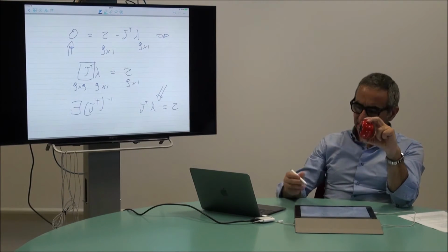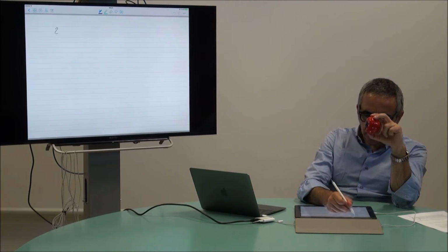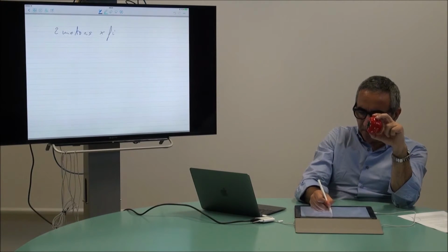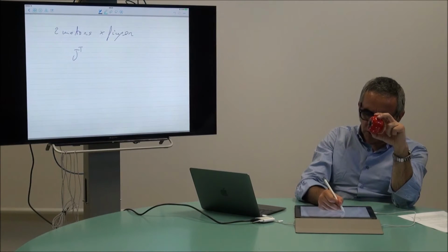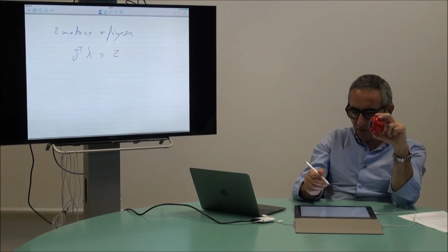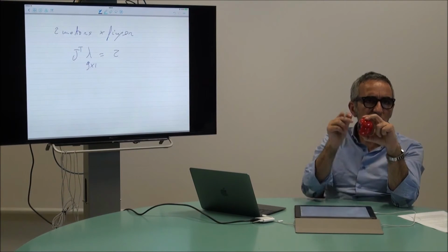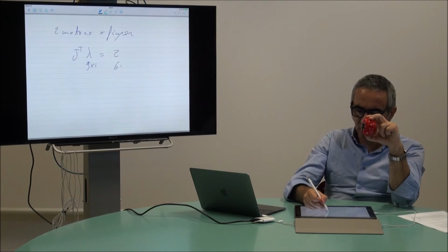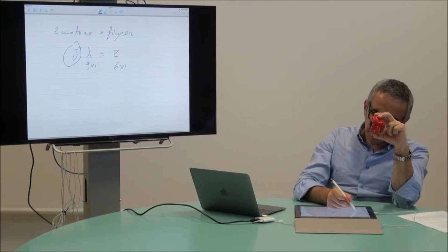So you have that the lambda are still, in case of 2 motors per finger, okay, then you have that your J transpose lambda is equal to tau is something like this. You have that lambda is still 9 by 1 because the physics does not change at the contact, but tau in this case is just 6 by 1. Okay, and matrix J transpose is 6 by 9.